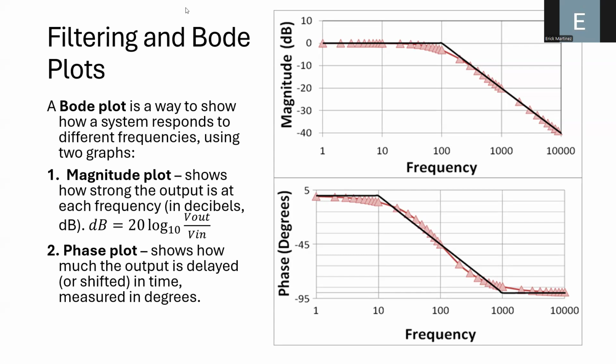And here at the right, I placed a picture of a Bode diagram. Here you can see in the y-axis the magnitude expressed in decibels. You can convert the magnitude to decibels by using the expression that I placed here. You need to take the base 10 logarithm of the output voltage of your system divided by the input voltage, and then multiply this result by 20.